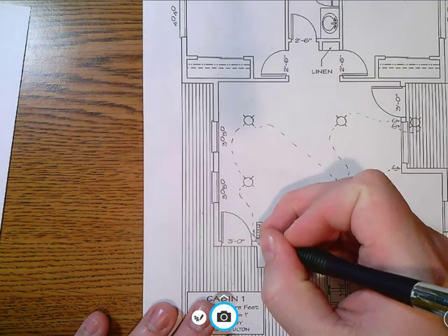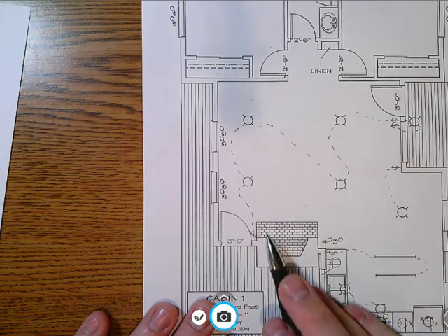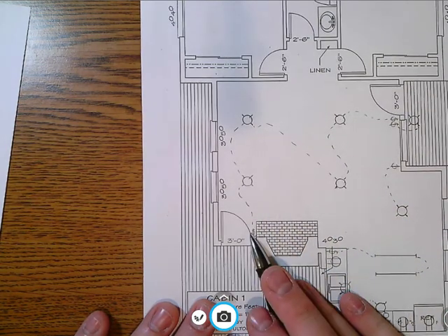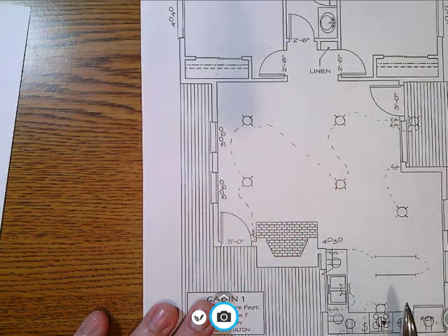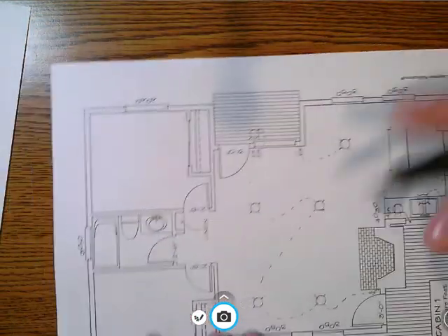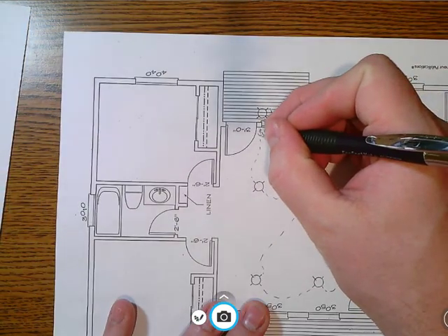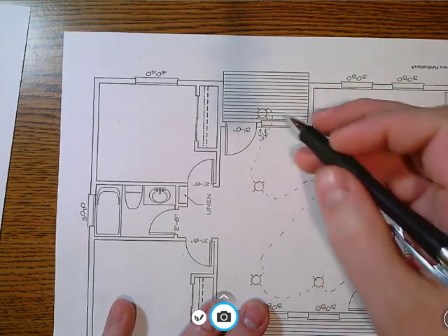Part of the reason you need to indicate it here is that the electrician needs to know he needs to buy 3-way switches and 3-wire lines to connect to these lights, so that when this is all coming together, we can put this in.